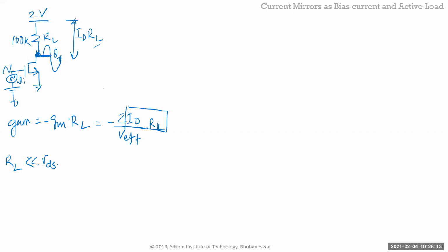So if I want the amplifier not to clip, for a certain input of voltage, where do I ideally want to sit? 1 volt, right? Because that way it'll allow me to go 500 millivolts up, 500 millivolts down, assuming everything remains in saturation still. And if I bias it at 0.575 volt, then if I go 250 millivolts, it's clipped. I have 750 millivolts down headroom, but I have only 250, so it's useless, right? So typically you want to bias it in the middle, right?